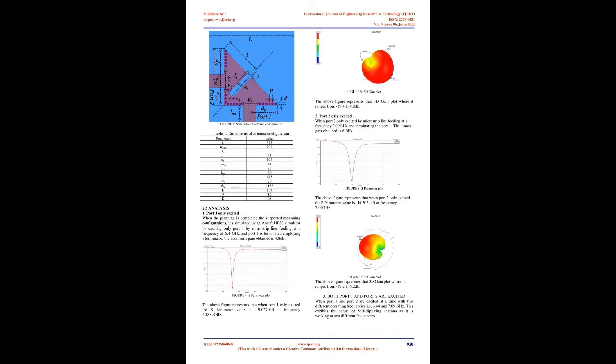1.2 HMSIW and QMSIW. It occupies large space because of the full-wave SIW antenna. A big miniaturization of the SIW antenna is achieved by applying the SIW half mode, HMSIW, and SIW quarter mode, QMSIW [11-12]. The HMSIW has almost the equivalent distribution of the E-field as the full SIW, although its size is half that. QMSIW is attained by dividing the HMSIW into 2 parts. Figure 1, HMSIW and QMSIW.